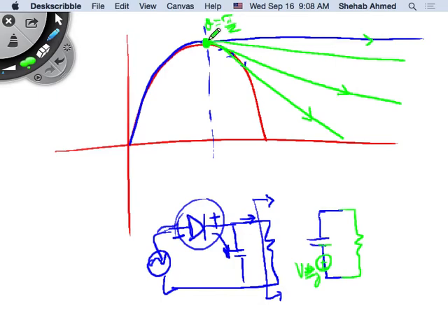But if I'm drawing a little bit of current, then theta moves a little bit. This green waveform will part away from that red waveform a little bit beyond pi over 2. If I draw more current, this theta will move a little bit further with this red waveform, right? So this theta value depends on how much current you're drawing out.